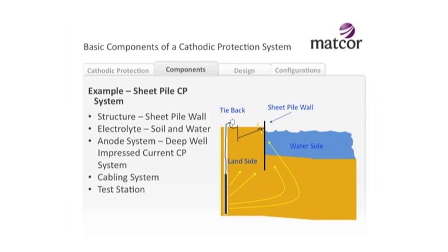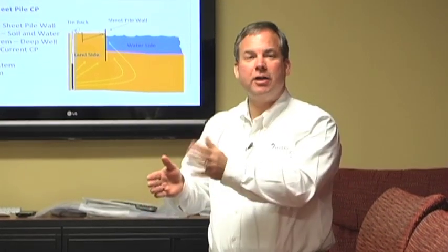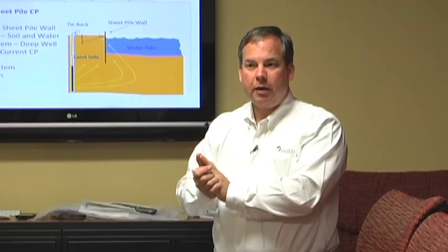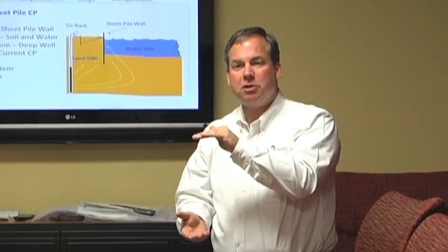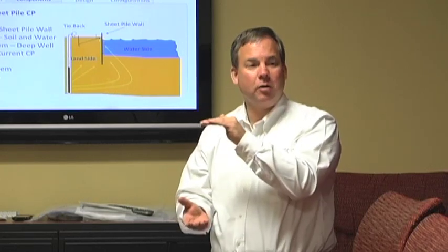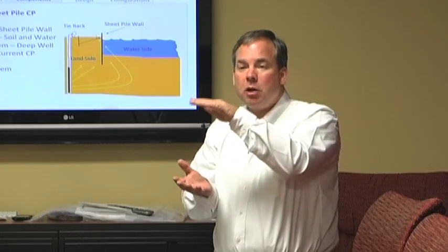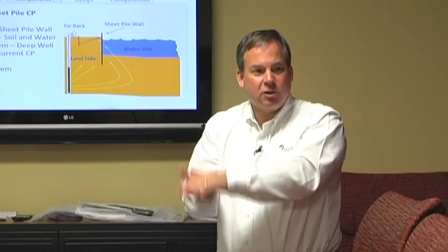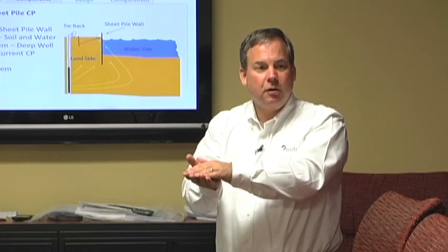There's actually a couple of places we're concerned about. There's the land side of the seawall where the sheet pile is driven into the land and you have soil side corrosion, okay? There's the very bottom of the sheet pile, which is in soil on both sides because it's below the water level. And then there's that area where the water is, okay? There's also a small area where there's the atmosphere and its tides go up and down. That could change in its height, okay?